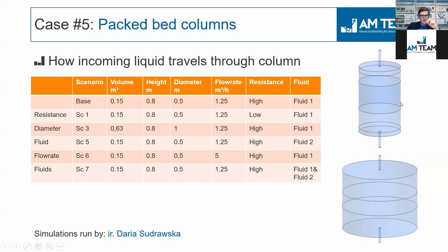In this case, we have been modeling a packed bed with a polymer packing that is actually susceptible to the kind of solvent you put on it. So if you change a solvent on a polymer, the polymer can actually start shrinking or expanding. If it does that, of course, the porosity of your bed, also the resistance of your bed, and finally your pressure drop over your bed, and also the flow dynamics through your bed, will all change. So just to illustrate it a bit, we have done this CFD simulation where you will see the